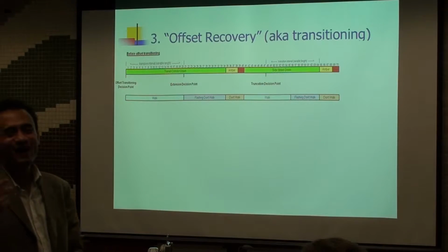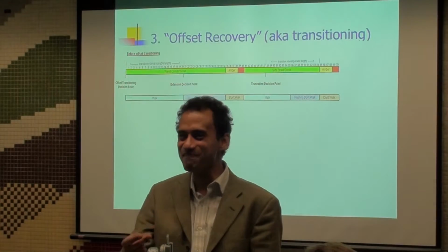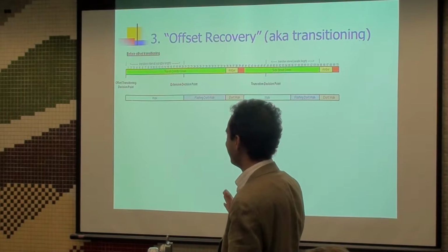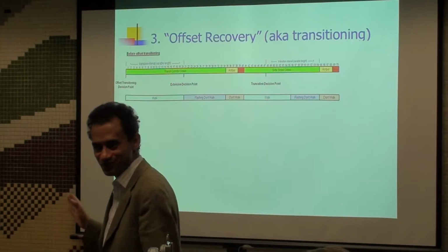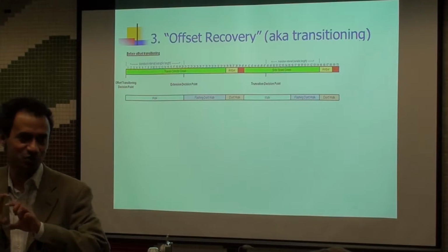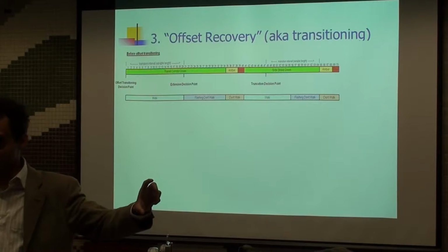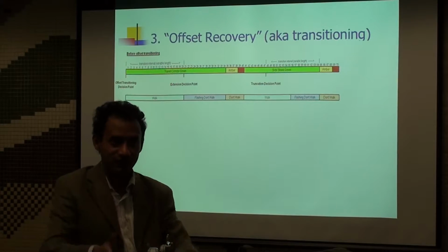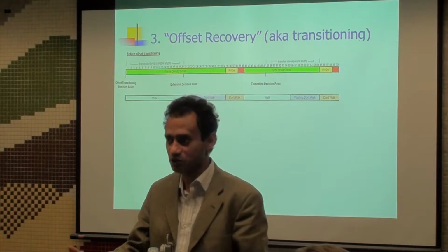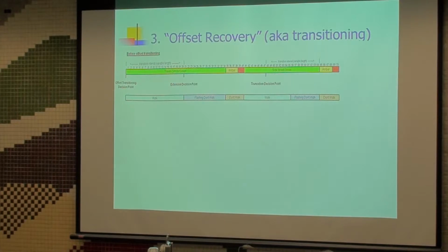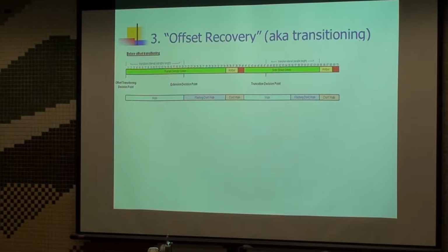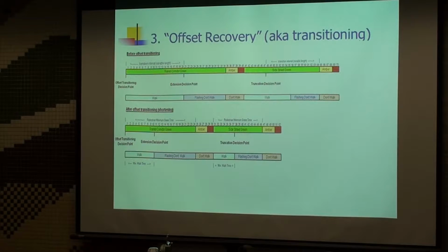Then you cannot all at once come back to the original green wave signal. You have to do it sequentially, one at a time. Otherwise, you cannot do all at once. You might get a queue in the other street, like the side street. That's meaning for the transit. So you have to do that, and it all depends on that particular signal that we are talking about. So there is a lot of planning involved, planning and engineering, signal timing, those kinds of things. So that's what we should be doing.